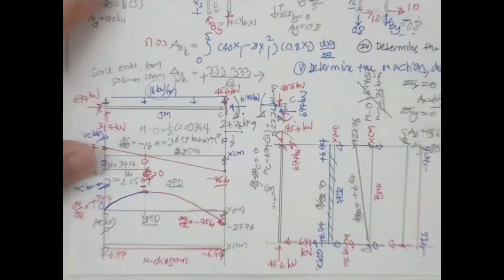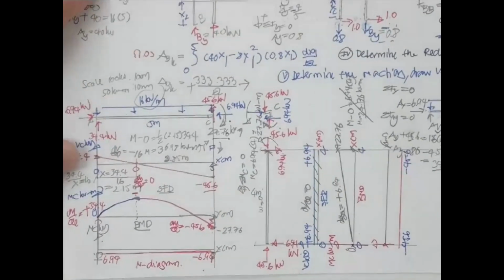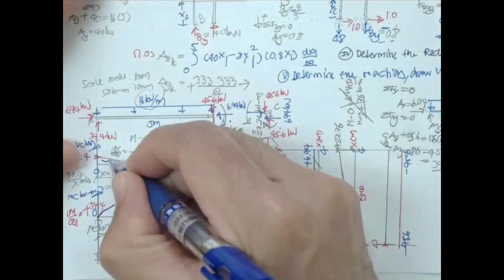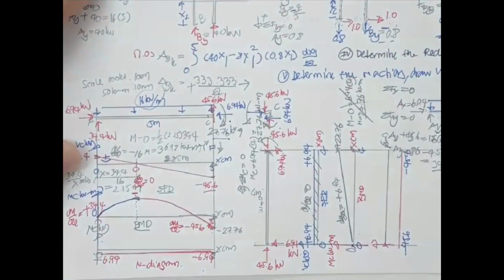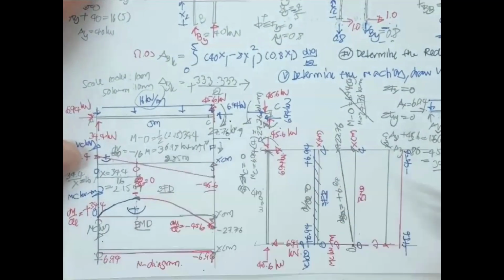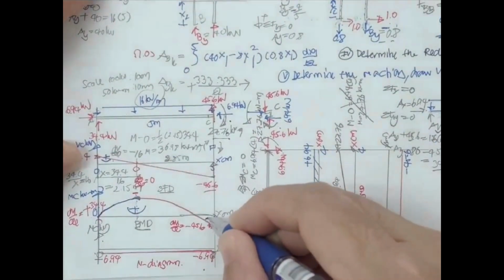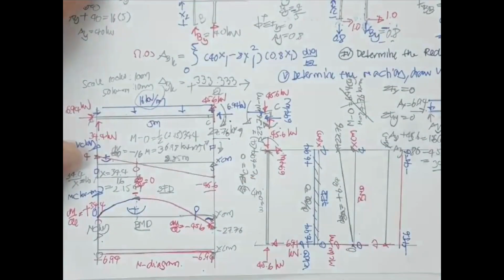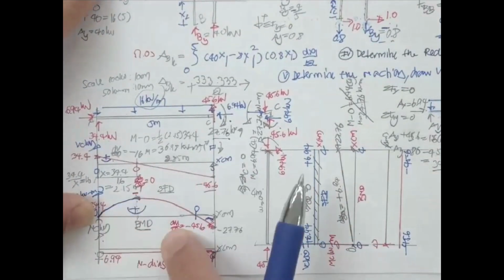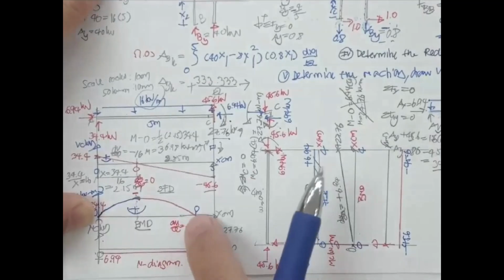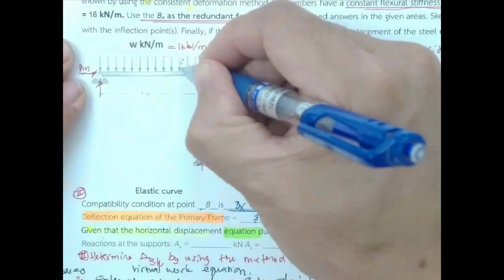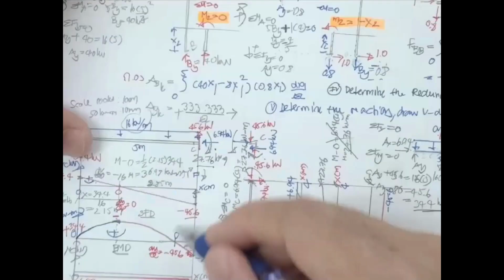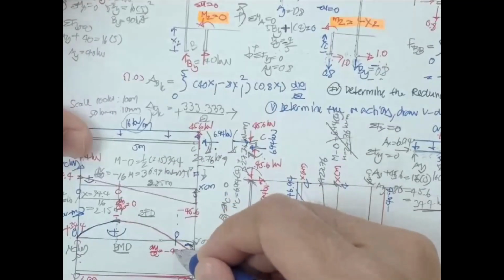Now, you get your bending moment. The bending moment will help you draw the elastic curve. Let's put it concave upward. Oh, sorry, this is here. Concave upward, and over here, concave downward. And this is going to be the point of zero moment. Okay, let me take you over here. Concave upward, and then going back to concave upward. So over here there is a point of zero moment, the inflection point.